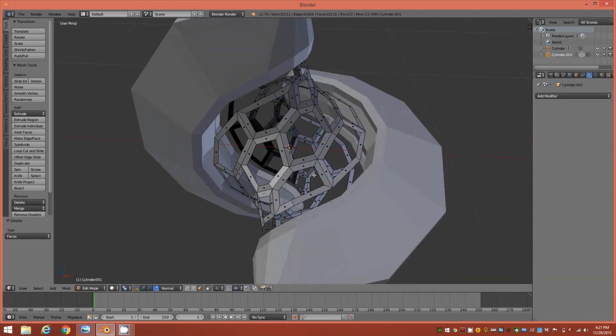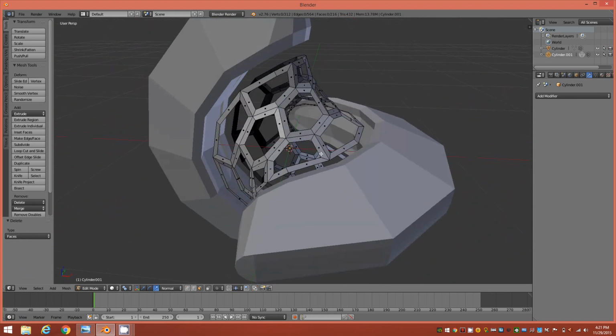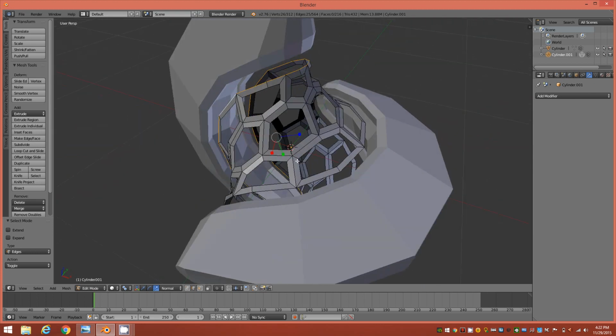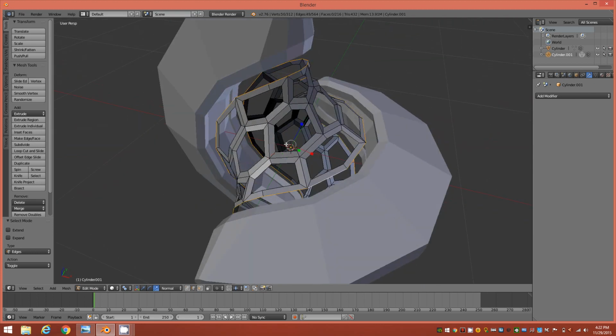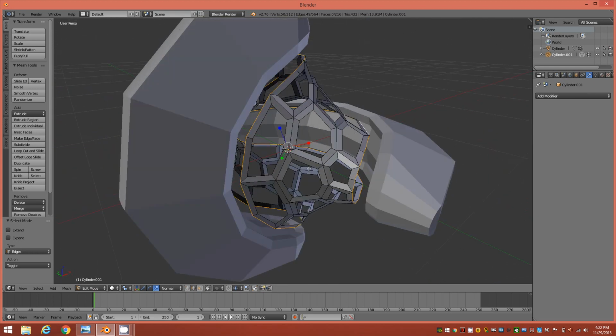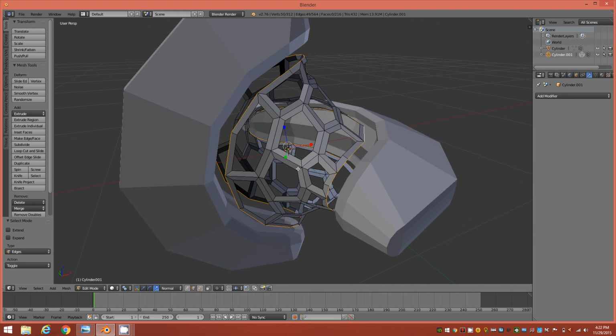Okay. All right, so now from here we could go ahead and switch to edge mode, hold down Shift and Alt, and select our edge loop all the way around on that side, and then we'll do the same on this side. Okay, so we're selecting those edge loops, and what we're going to do next is I think we'll go ahead and extrude.